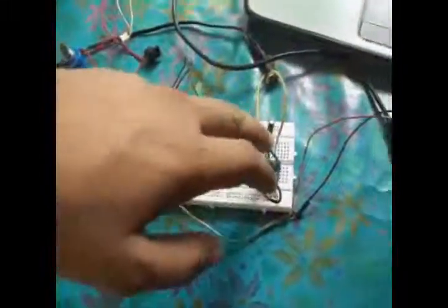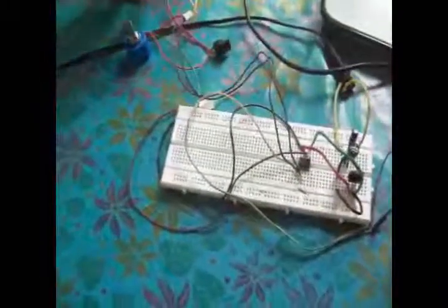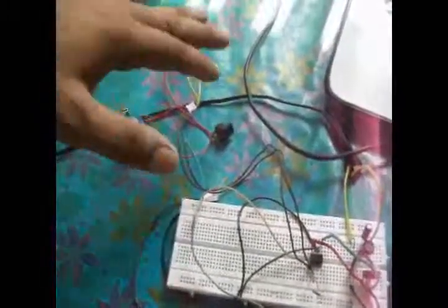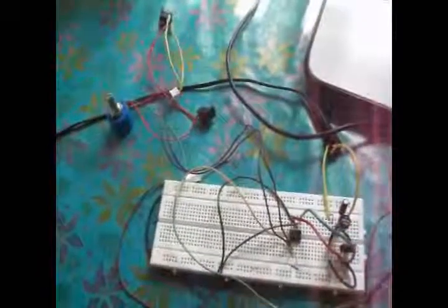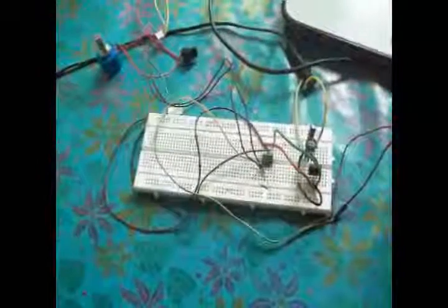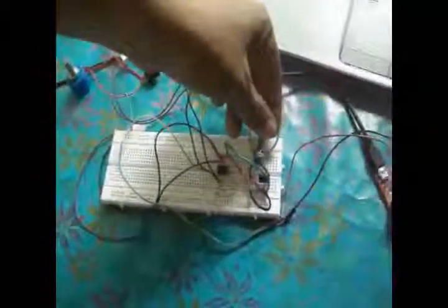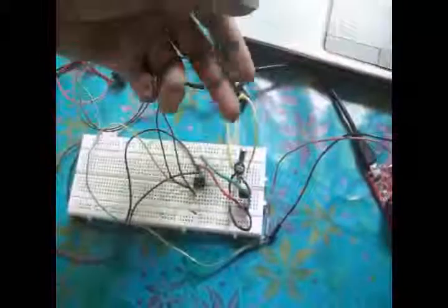Now we are using the 32 volt supply because the laptop power supply input will be about 19 to 20 volts. The laptop battery has to measure about 11.1 volts, which means the bias has to be greater than 20 volts. So we are using a 32 volt supply. Since the current drawn by the amplifier is very little, we are just using a simple 100 microfarad capacitor.